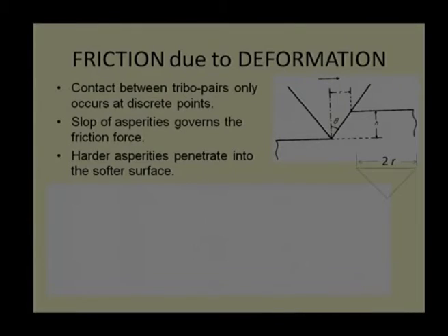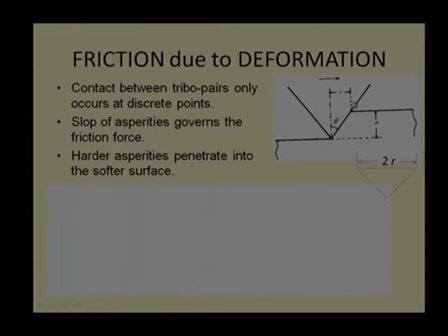So, let us explore what deformation theory says. We can assume different kinds of asperities, because surface roughness plays an important role in deformation. Let us take the first example, a conical asperity, and we are assuming the same cone radius for all asperities. There may be n asperities on a surface area which we are defining. This conical asperity is pushed to some depth in a soft material, that depth is h, and we are trying to push this asperity so that sliding occurs, right.